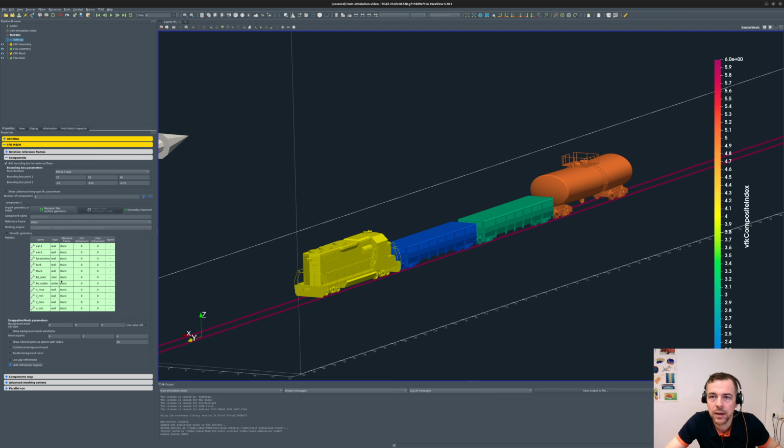I need to say a couple of things. For example, the walls of the virtual tunnel are virtual. So I need to go with the symmetry wall type. It's a kind of boundary condition which says there's no friction at the wall, but the bottom is the standard wall. So it's a wall.